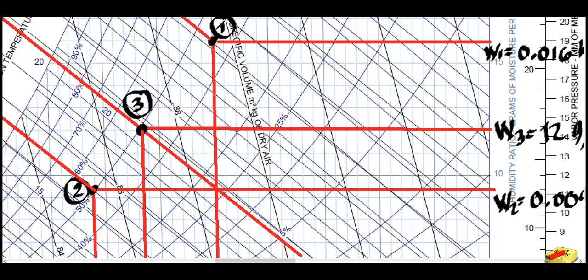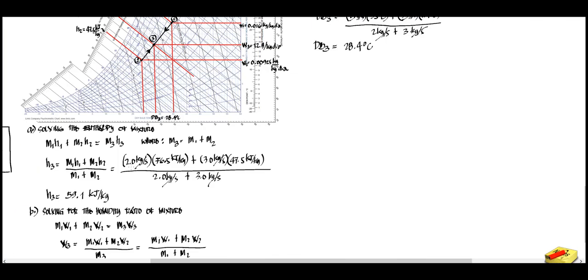Okay. So let's draw now the process. Draw the line. Since they are mixing, we draw the line here. Okay. So that's where it flows. The air enters and mixes at point 3, and point 2 also mixes at point 3. Okay, that solves the problem. So it's easy, it's not very complicated, no?